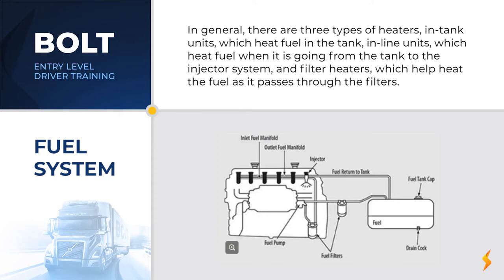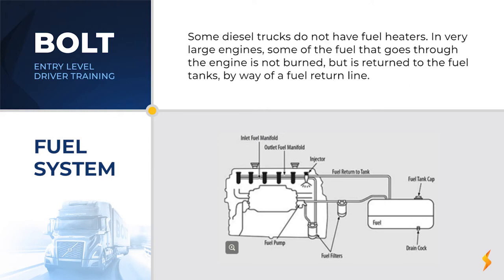In general, there are 3 types of heaters: in-tank units, which heat fuel in the tank, inline units, which heat fuel when it is going from the tank to the injector system, and filter heaters, which help heat the fuel as it passes through the fuel filter. Some diesel trucks do not have fuel heaters.